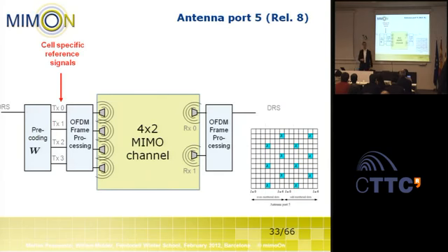This is done using user-specific reference signals. On top of the cell-specific reference signals that each user receives to estimate the MIMO channel, we now have some specific reference signals, as illustrated here in the time frequency domain. These signals are transmitted, or included, before the pre-coding. So before applying beamforming, the reference signals are included. In fact, we transmit these reference signals with the selected beamformer.